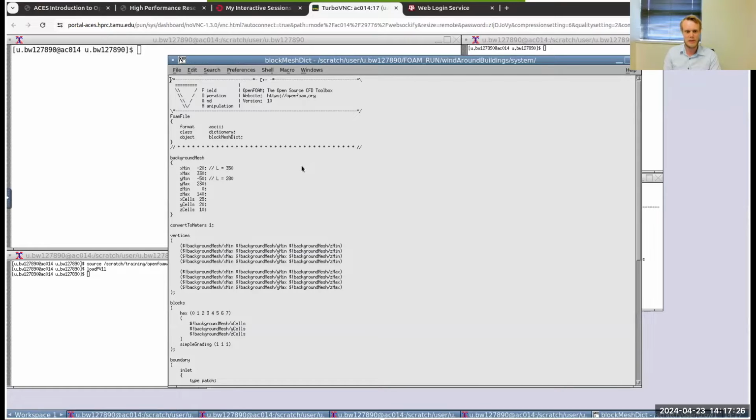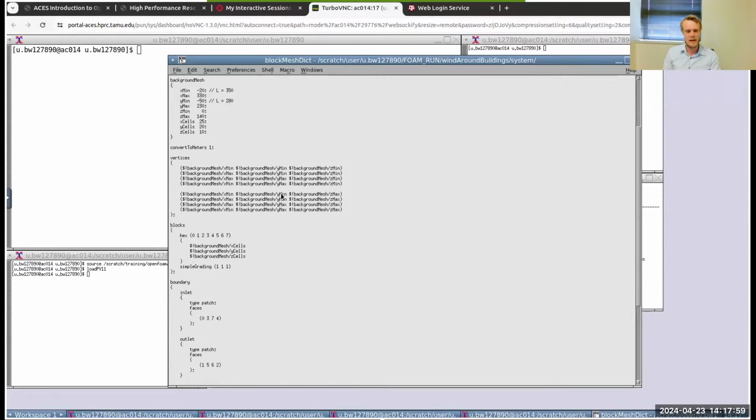You can bend and warp the blocks to bend around airfoils and stuff like that, so it can be useful for that. But for any kind of arbitrary geometry, this is not very useful. For that, we have the OpenFOAM mesher called snappyHexMesh. But snappyHexMesh requires a background mesh, so that way we always still have to use blockMesh. In blockMesh, we basically define vertices X, Y, and Z, and then from those vertices, we define blocks.